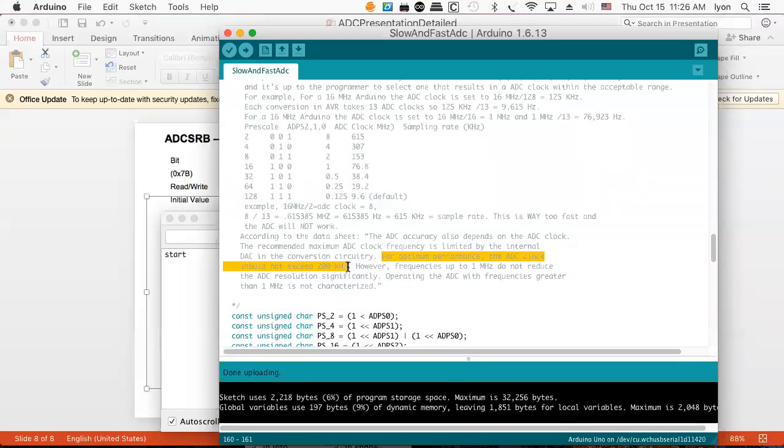That means I'm going to be down in the, I don't know, 9.6 kilohertz sample rate, because that's 125 kilohertz. Next one up is 250 kilohertz. So that doesn't really float my boat, because if I'm sampling at 9.6 kilohertz across 2 different ADC converters, I'm really down to a total sample rate for each converter of perhaps 4.8 kilohertz. And that means my maximum input frequency, according to Nyquist, is going to be half of that, which would be 2.4 kilohertz. And I really want audio to go up above 2.4 kilohertz.